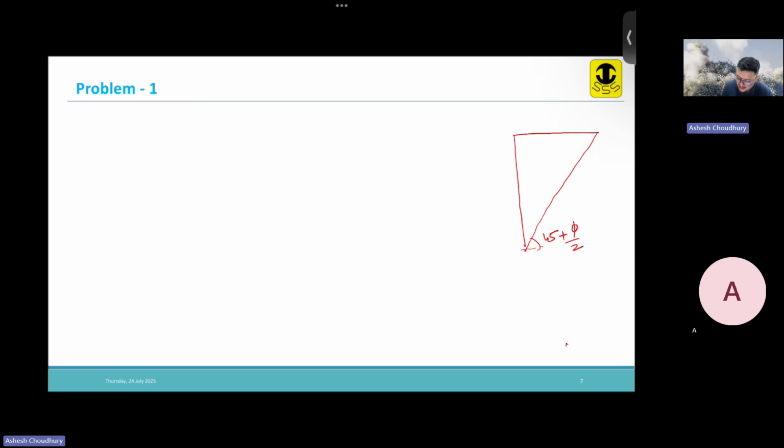Now, what will be my length of reinforcement? The length, so we know this height, total height I know. Now at any depth Z, if I want to find out the length of the reinforcement, that is LR plus my embedment length.